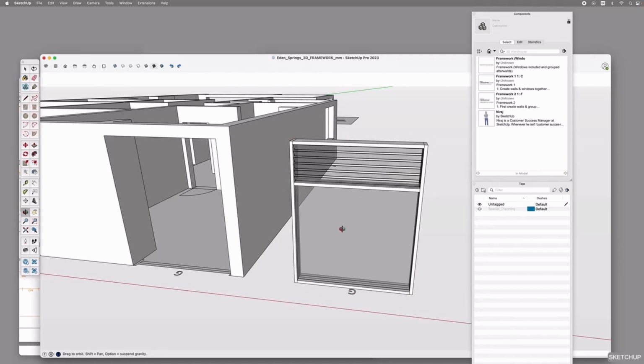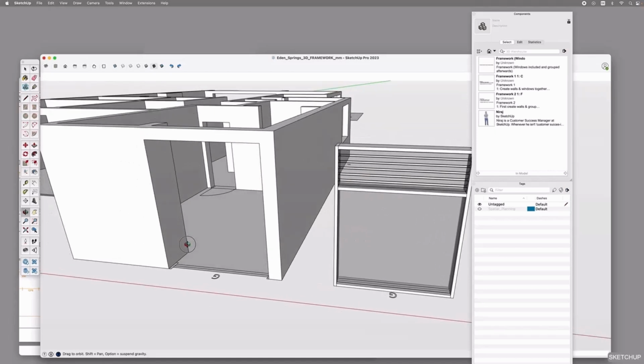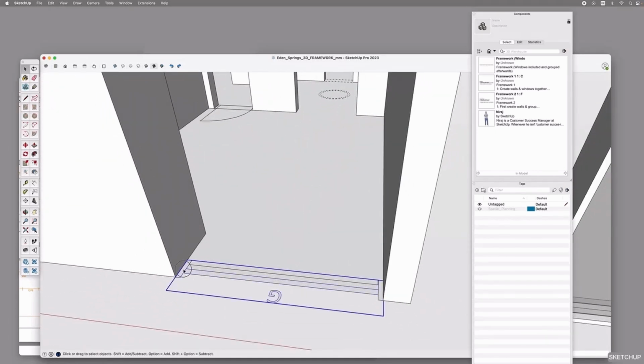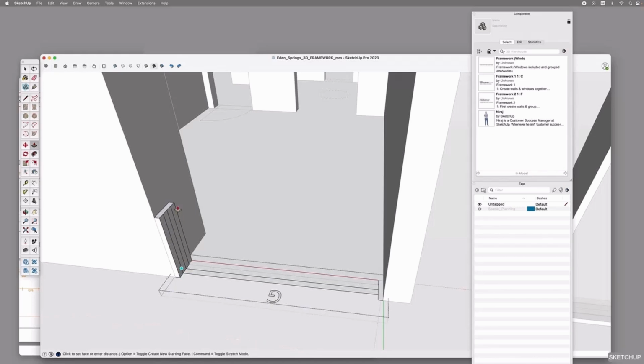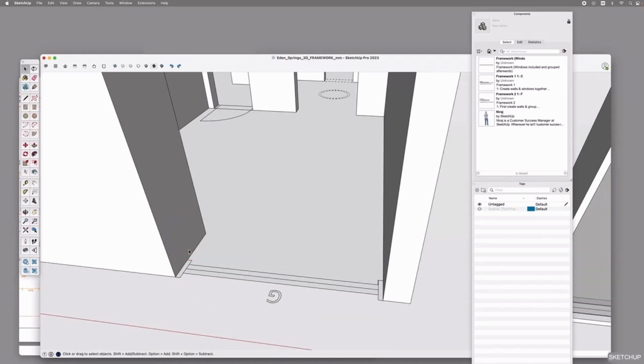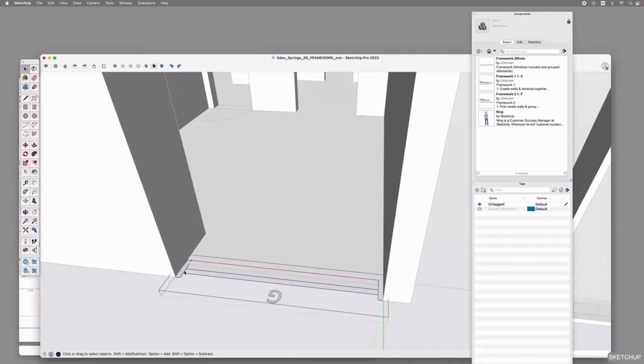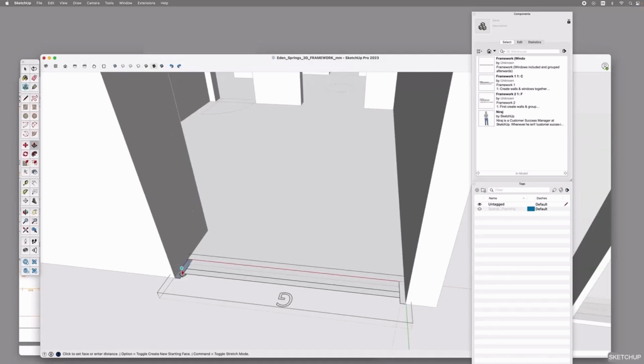We could potentially use the surface we got from the 2D spatial plan, but it's not 100% necessary. You could simply also just use this as your reference and create another rectangle outside of the group. In this example, I will use the existing surface we have from this symbol. We double-click into the group and select the outside frame surface. Then we use our push-pull tool and hover over the endpoint and release.